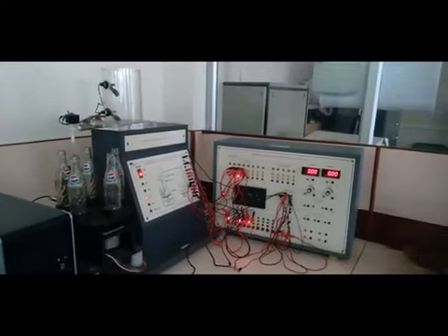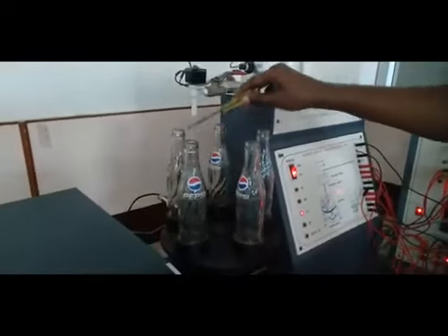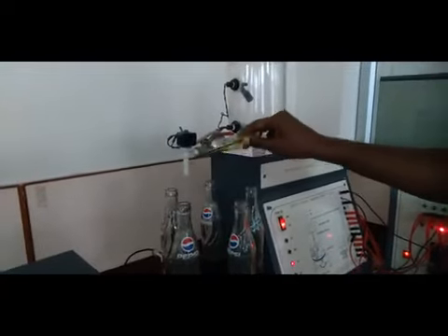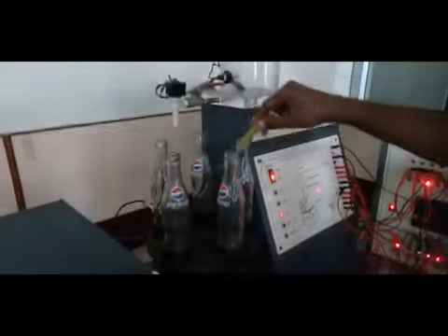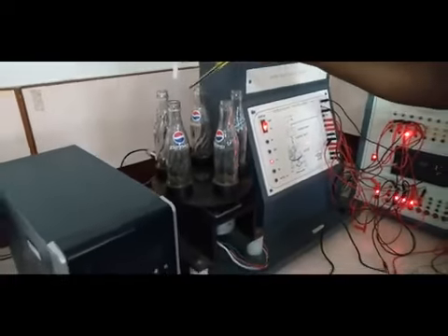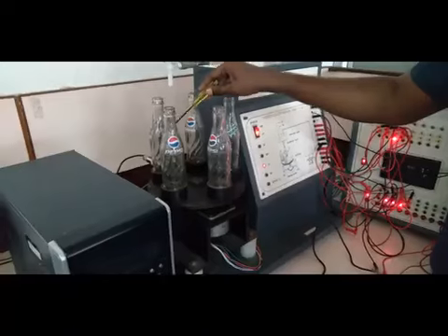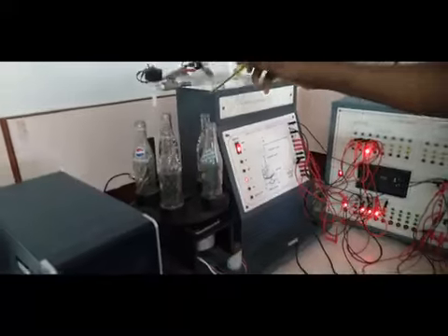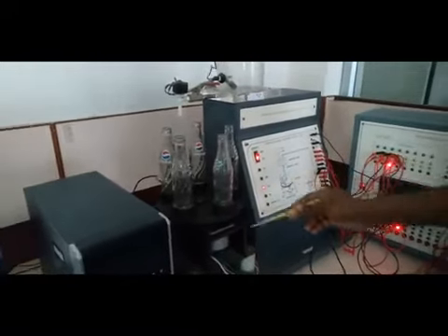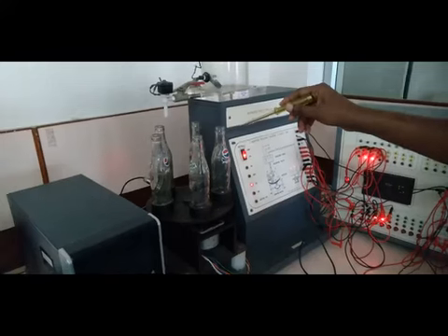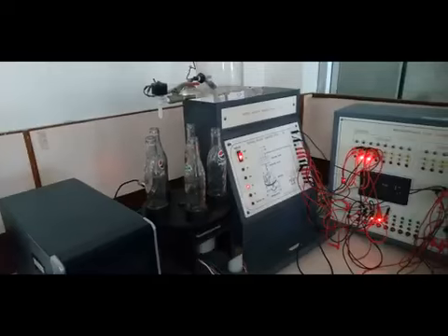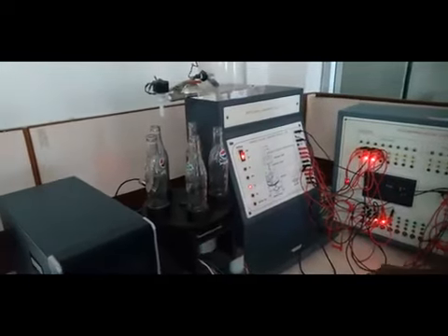This is rotating. When the sensor becomes true, due to our program it is stopped. Now the solenoid valve is open; since we don't have fluid, it is not coming, but it will come. The stepper motor is stopped because we have the bottle and the bottle position at the same place. Then the timing is over and it starts rotating again. Then the second bottle comes, it stops and delivers the fluid into the bottle. This is the bottle filling system.